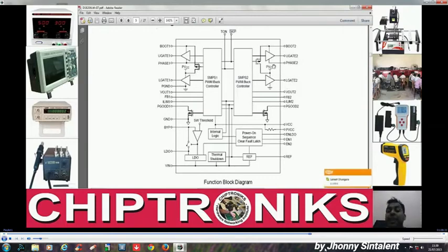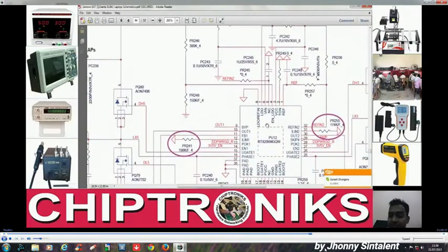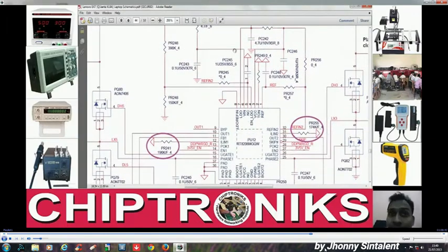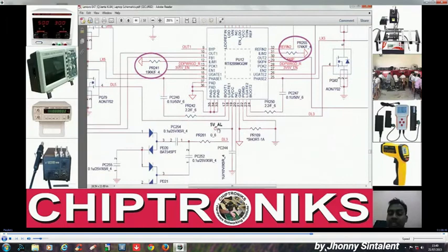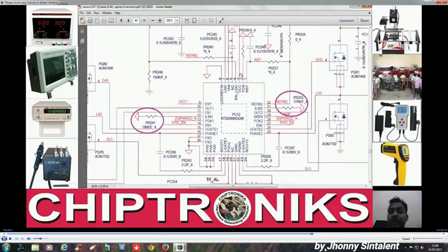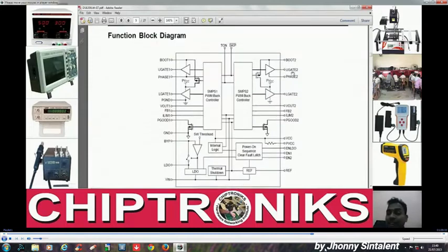This is connected to the PVCC. As we have already spoken, PVCC, very important. What was the first point? It gets Vin, then LDO is released. LDO is connected to the VCC and PVCC. So 5V_L is generated through LDO, and this is going to VCC and PVCC. So if VCC and PVCC are not there, then it will not generate the U gate 2 and L gate 2, right?